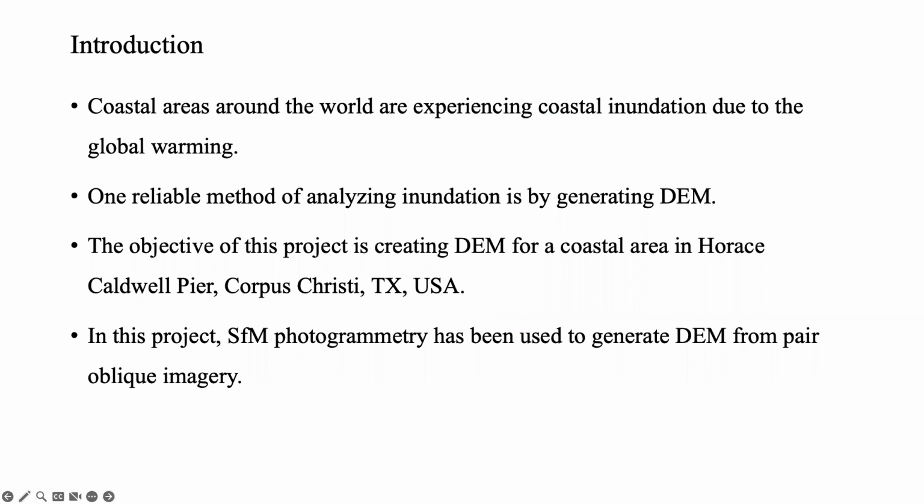Coastal areas around the world are experiencing coastal inundation due to global warming, and one reliable method of analyzing inundation is by generating a digital elevation model. This project aims to create a digital elevation model for a coastal area at Horace Caldwell Pier in Corpus Christi. In this project, I've used SFM photogrammetry to generate a digital elevation model from a pair of oblique imagery.